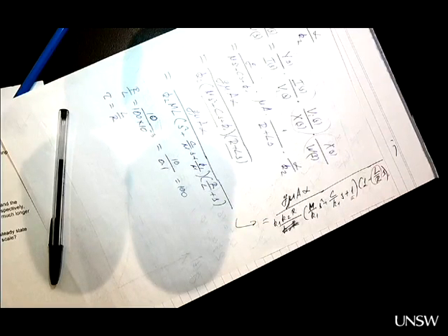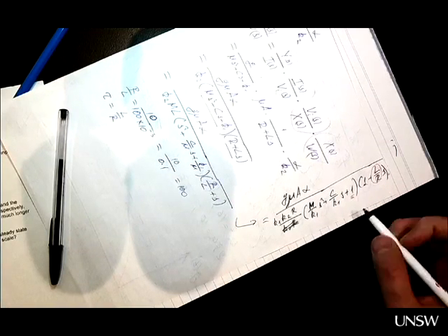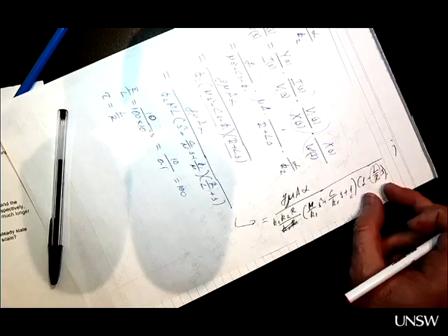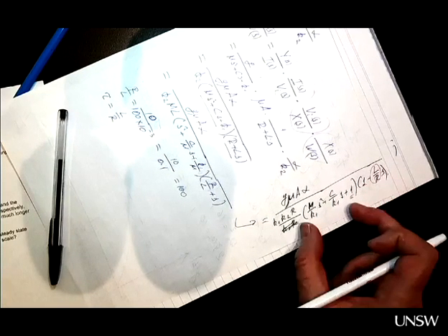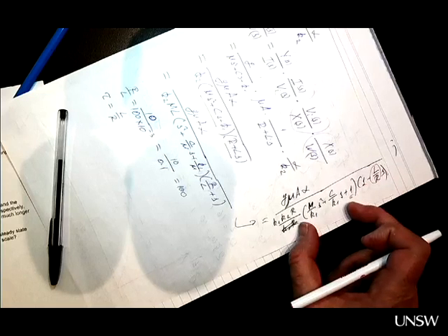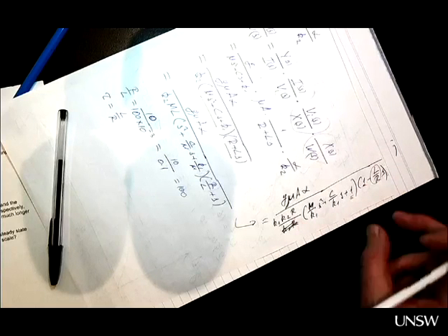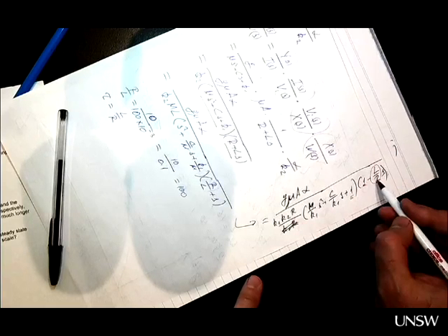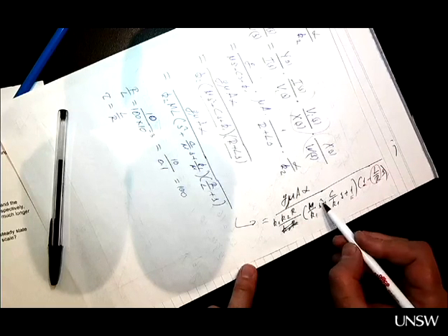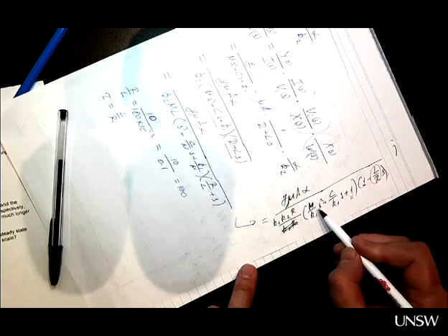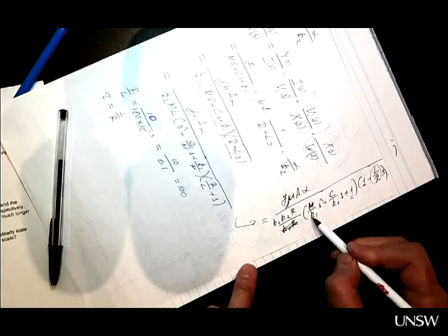When you have a non-dimensional form, you read what multiplies s. That is the time constant. It's very simple with the first-order system. We'll see about the second-order system in a moment. But with the first-order system, what multiplies s is the time constant. Here, what multiplies s squared is the product of two time constants. So let's see how we deal with this one.